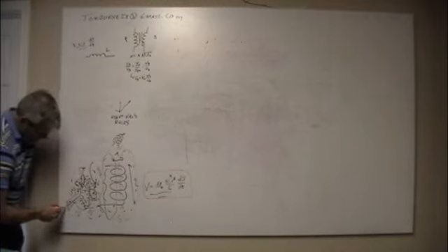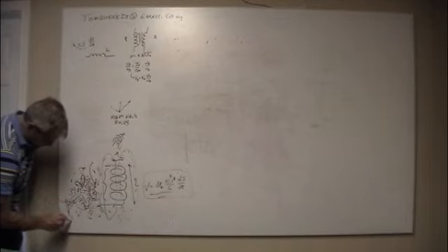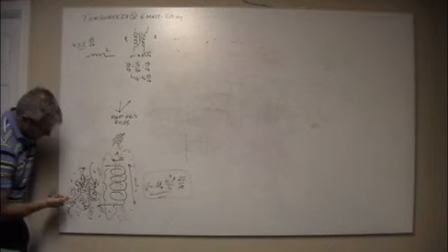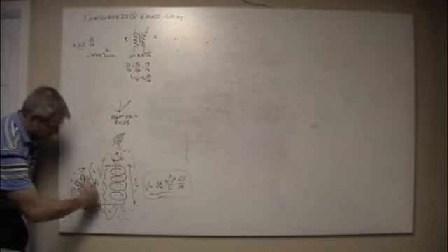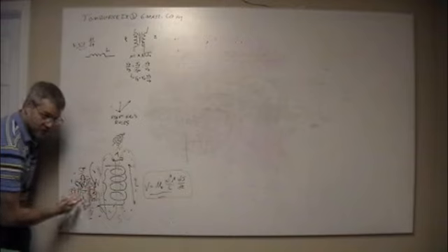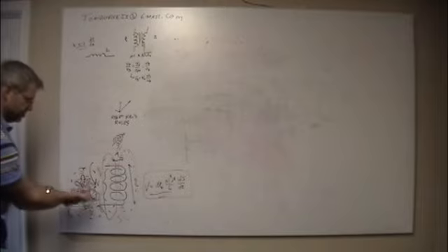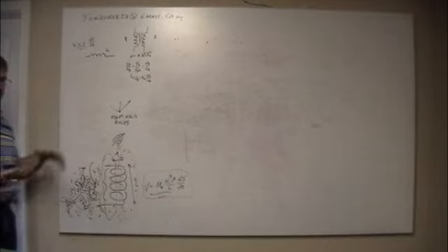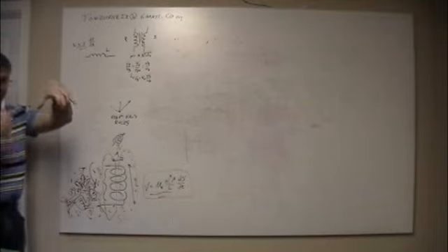And I've got a slip ring back here that connects here, and connects there. So this is positive voltage and this is ground. But when it flips to a certain point, then it hits the other one, and now current's flowing the opposite direction through it. So now the poles switch. What you're doing in your electric motor is switching your poles back and forth. And you've got two permanent magnets that sit there and attract the pole around and keep it going.